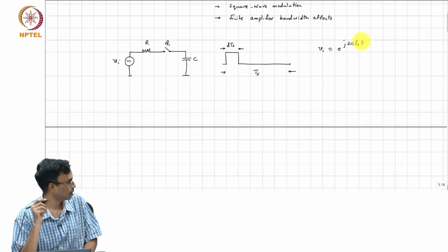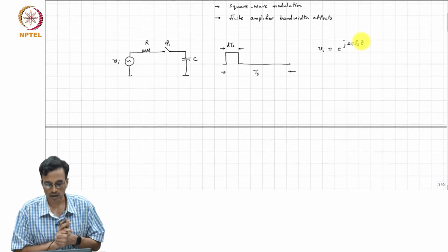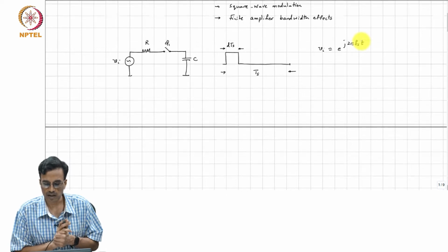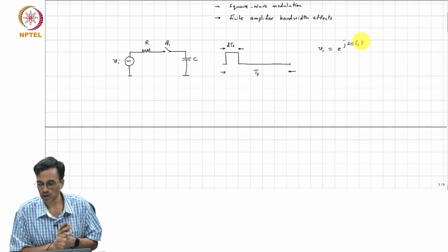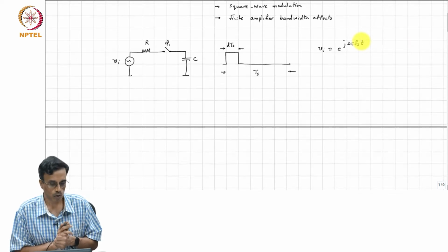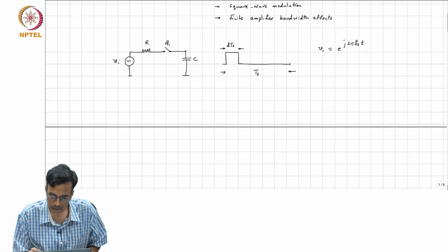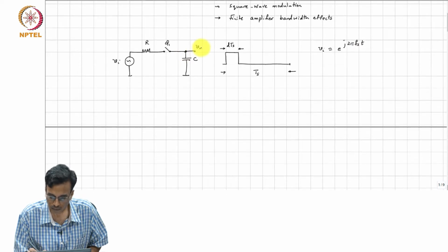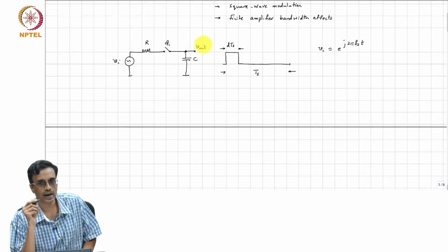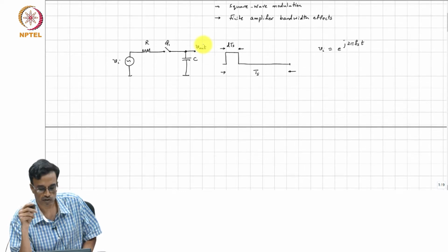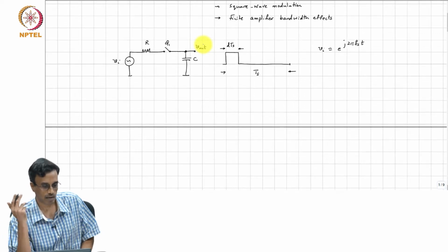So, the input is a sinusoidal tone or a narrowband tone signal which resides at around multiples of the frequency at which the switch is opened and closed, and the output therefore, the dominant component of the output will be at DC, right, because you are sampling a sine wave at Fs at roughly the same rate.